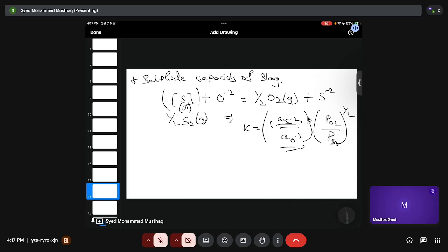Phonons are very important in ceramics and ionic compounds, because there you do not have that much free electronic structure. Phonon motion is sluggish compared to electron motion, so thermal conductivity is low. That's why your slag acts as a good thermal barrier. So these are the different properties of slag.